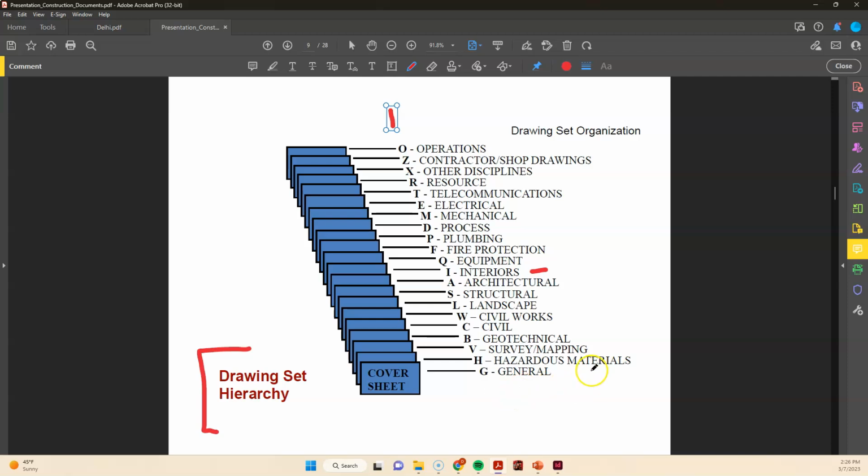In residential and commercial buildings, what we typically will find is civil, which we just discussed, landscape occasionally if it's involved, definitely in a bigger project. Again, structure, architecture, interiors maybe. I've worked with interior designers, but we just don't break out the sheets as I sheets. That would have to be a really big job, I would think. Same with geotechnical. Those are the engineers that come study the earth, do boring tests, but they don't usually make drawings. They give their report to the civils and they incorporate it. Same way, interiors will often do their work, and it ends up on architectural sheets. For smaller, more modest projects, that's what you would expect. Plumbing, mechanical, and electrical are the most common ones for commercial projects.